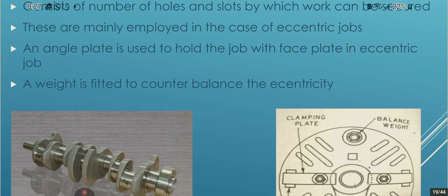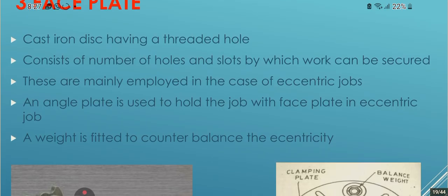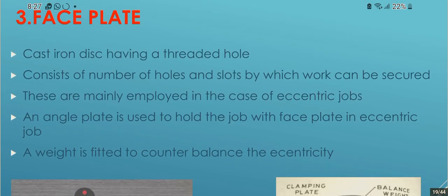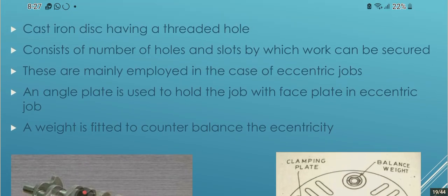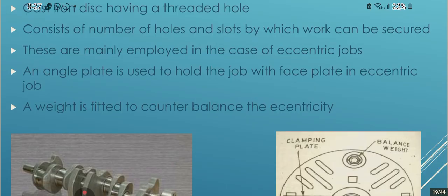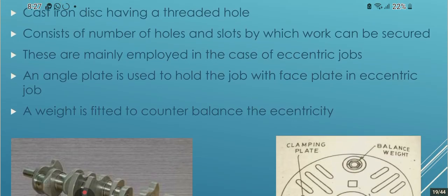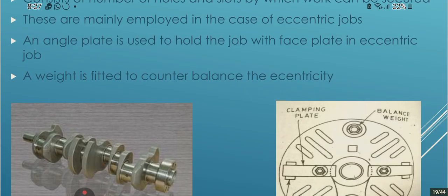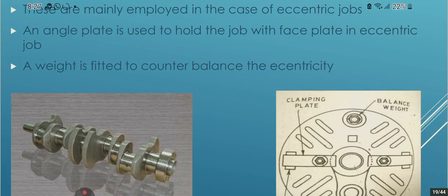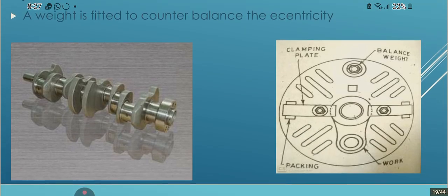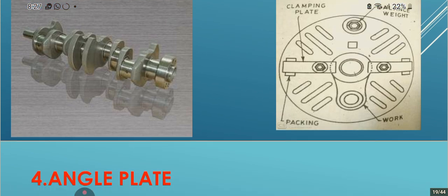Faceplate. A cast iron disc having a threaded hole. It consists of a number of holes and slots by which work can be secured. These are mainly employed in the case of eccentric jobs. An angle plate is used to hold the job with faceplates in an eccentric job. A weight is fitted to counterbalance the eccentricity.